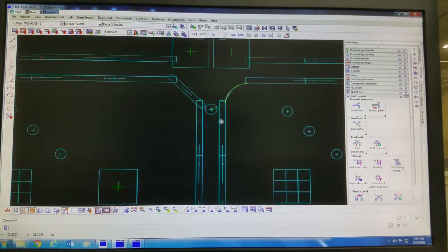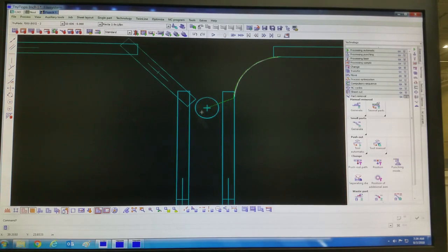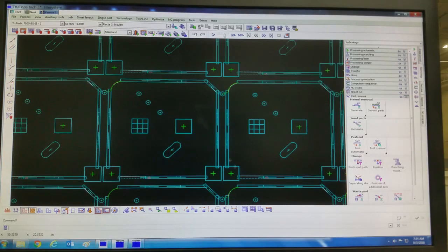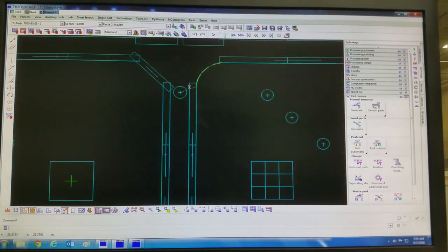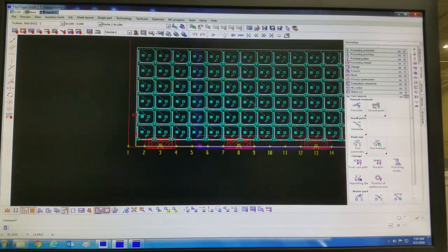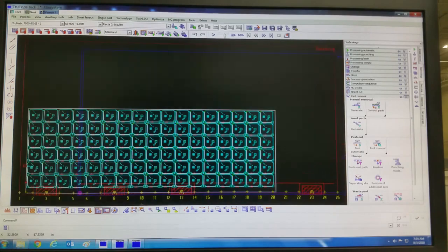Usually be careful as you change the position for the pre-punch or for the laser cutting, because this can affect the other part. So usually after the nesting and processing, just check it and make sure that one part doesn't affect the other. Yeah, so basically this is it.